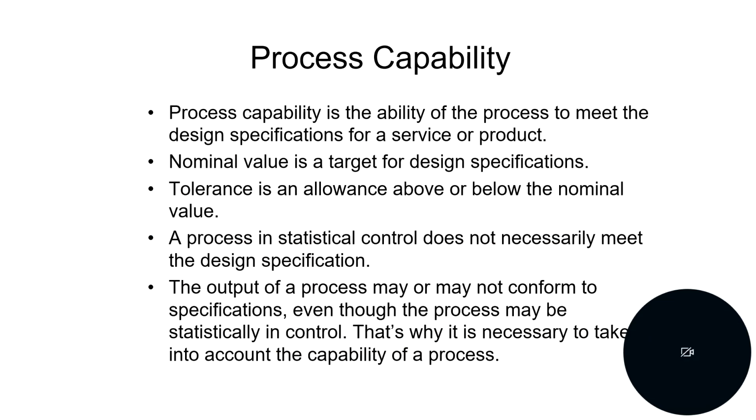And then we have process capability. The capability analysis is performed only after a process is shown to be statistically in control. This means it shows only random variations. It determines if the process's inherent variation is small enough to fit within the design specifications. If it is, that means the process is capable. So for example here, after we confirm the stability, a study will show that 99.73% of output falls within the customer's acceptable tolerance range, meaning it would be capable.